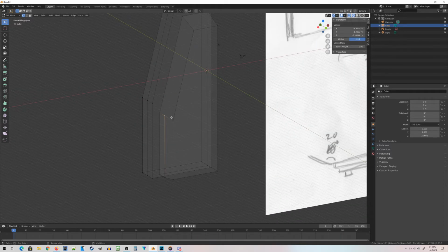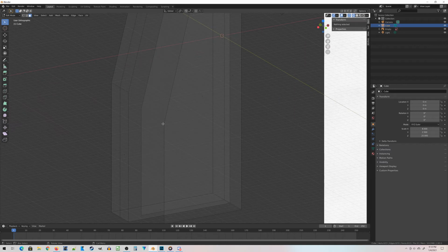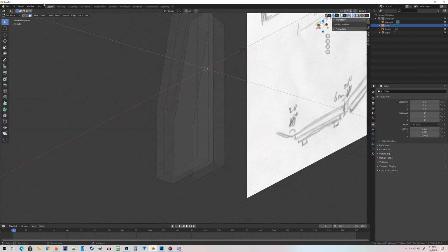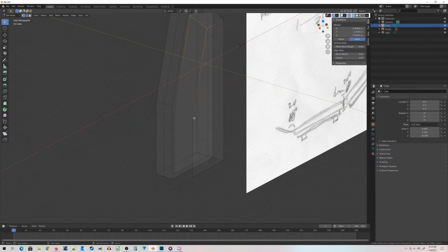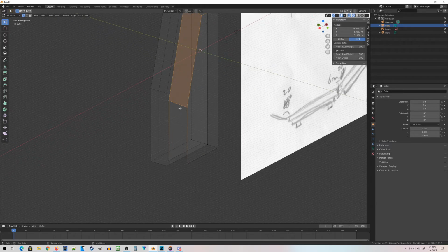Down here, I am going to do something similar. I'm going to delete this vertice, which will delete all those faces. I'm also going to delete that vertice at the bottom there. So I'm really hacking things to pieces because, well, this is what happens when you do things wrong. You have to start hacking things to pieces. So, okay, now I got to rebuild these faces. So I'm just going to select 4 vertices at a time. Press F, build the face. And then repeat that process.